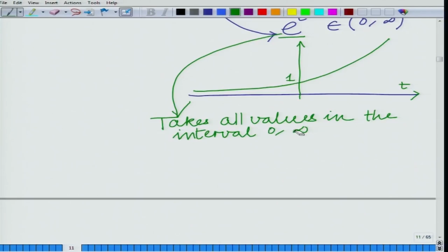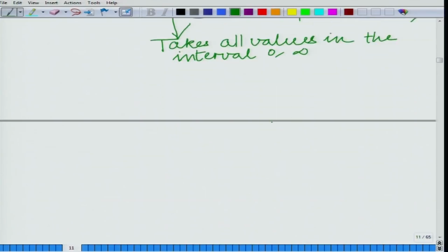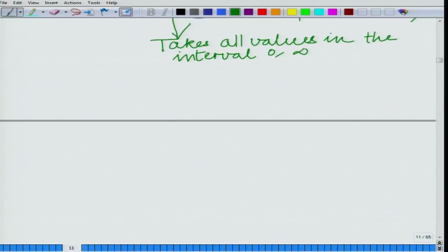Okay. And on the other hand, we have also a digital signal. A digital signal is a discrete time signal. A discrete time signal, which we have seen, is only defined at discrete time instances and can take only values that belong to a discrete set. In addition to being a discrete time signal, a digital signal takes values only belonging to a finite set, that is, it can take only one of a possible finite set of values. Okay. So, a digital signal